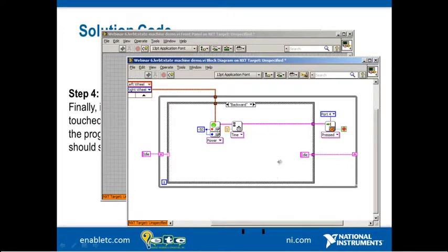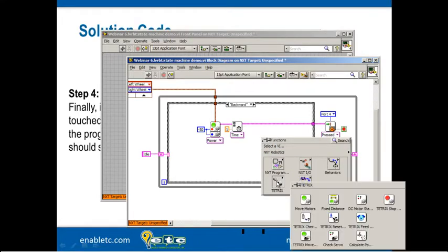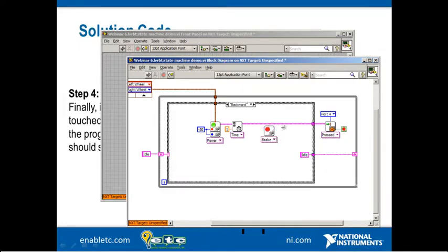And the last piece we need is to actually stop the robot after moving backward for 1 second. So we can go again to our Tetrix palette, our Tetrix stop DC motors, drop this down, break our sequencing NXT wire here, and insert the break instead. Keep everything nice and lined up, and wire up our motors constant.